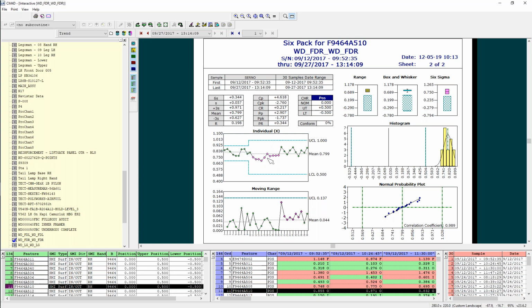Well, we can set what are known as conditional stylings for trend points, as well as for control charts, for any data that happens to be trending up or toward a limit, or anything that violates any other control statistic. So we do have ways of changing the data markers if a point is out of tolerance or violates some control limit or behavior.